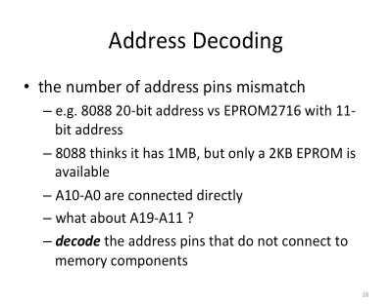That means it can access 1 megabyte of address space from 0 all the way to FFFFF. For this EEPROM chip, the 2716, we know it's a 2K by 8, so we have 11 bits for the address.